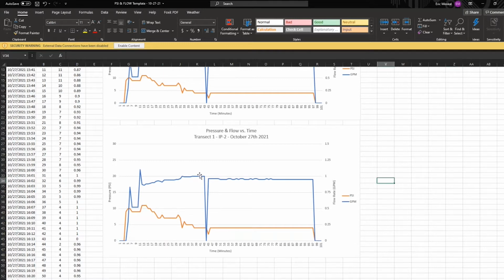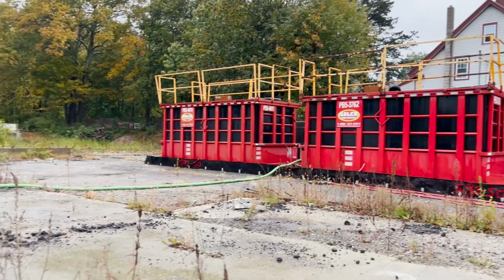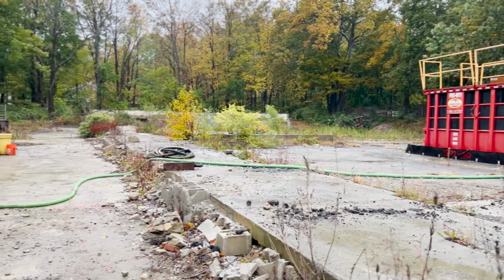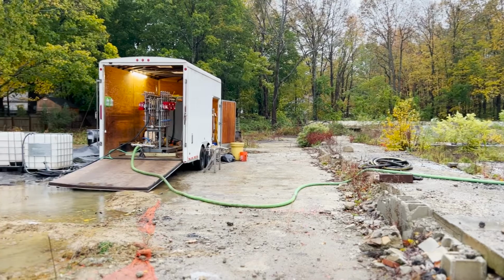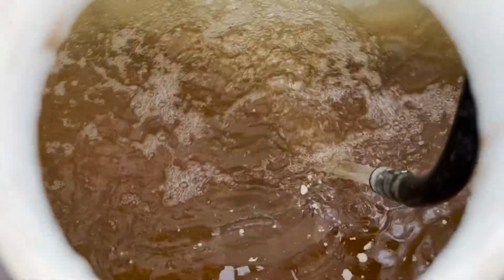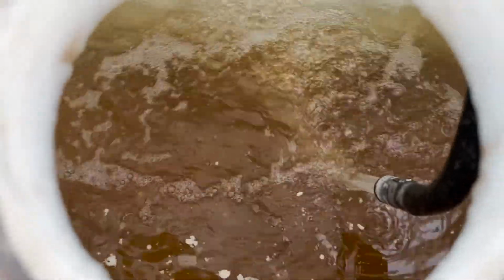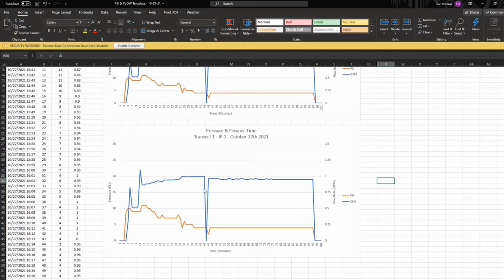For this project, we utilized large-scale tanks for staging water and deoxygenating the water. Water was then transferred over into smaller batch tanks where we could add the liquid and the dry amendments and blend them together in 250-gallon IBC totes. So we were mixing 250 gallons at a time, and when you're running up to 10 legs, even at 1 GPM each, we got to switch over every so often.